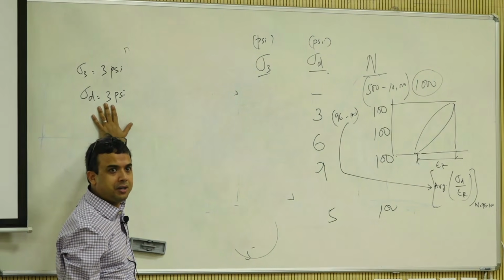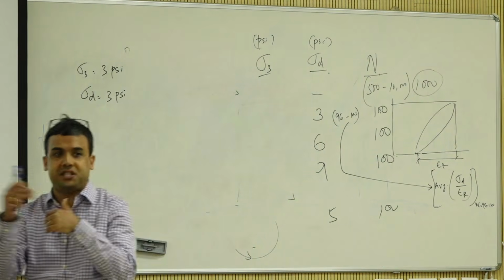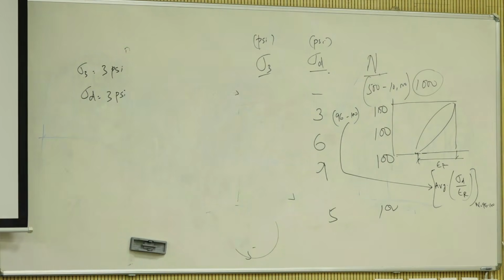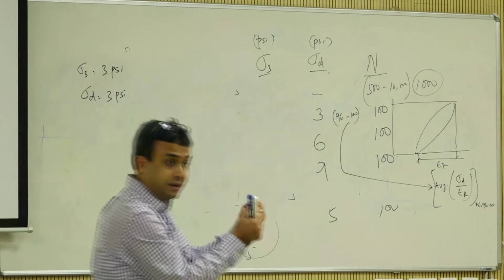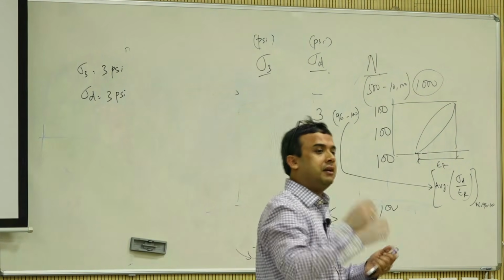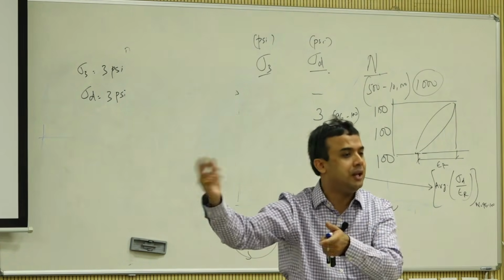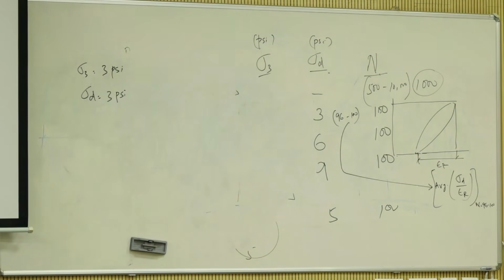Stress controlled, right? Because you are not specifying how much strain to apply or how much deformation to apply. You are telling how much stress to apply. So strain to measure, exactly. Strain you are measuring. It's not controlled. It's about what you are controlling, right? So it's basically like telling your car to go at 60 miles per hour and then measuring your fuel economy. What are you measuring versus what are you controlling?